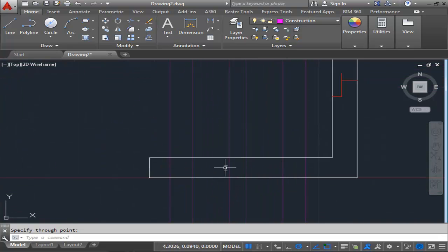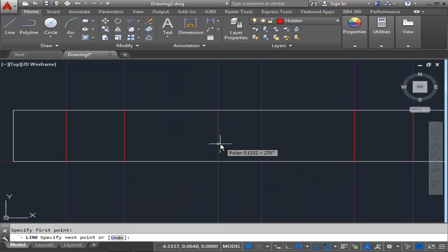So in between these lines here will be where my hidden lines go. So I'm going to switch it back to hidden. I'll go to my line and basically trace over the construction lines. Again, this is what makes drafting sometimes a lot faster. Now for the middle section, again, it has a depth of 0.130. I'm going to go across to the intersection and then back up.